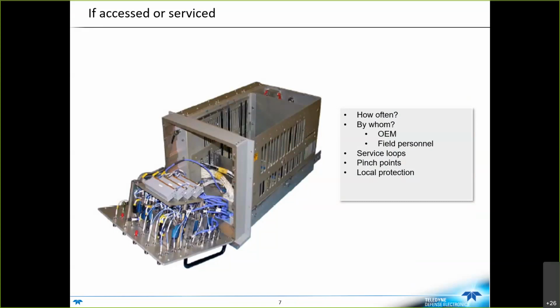Well, then let's talk about how often. Who's doing it? Is it OEM manufacturers that are only going to be opening that panel, or is it field personnel? And if it's field personnel, what do they really need to do? Is it just opening to this amount that you see here, or is it something that's going to have to be open and closed many times? A choice of cable might change because of the frequency of how that happens. If it's being flexed a lot, we need to take that into consideration. If you can envision how that's going to be up front.